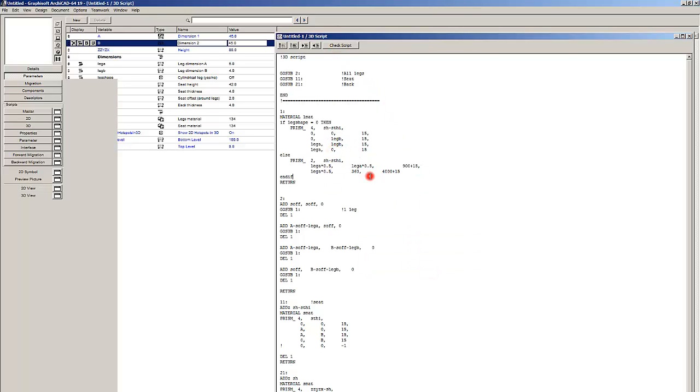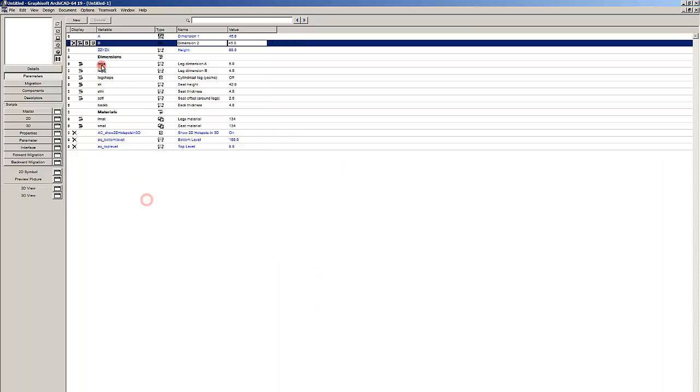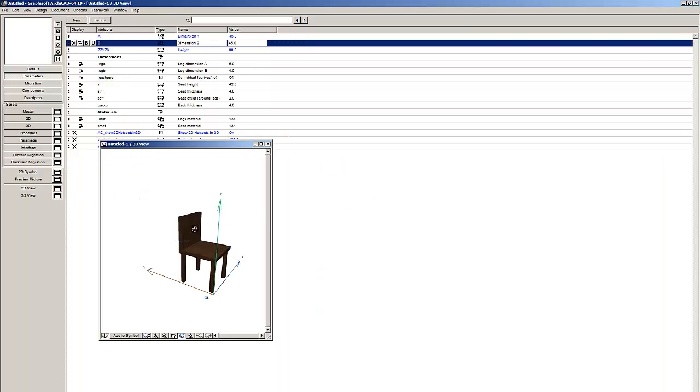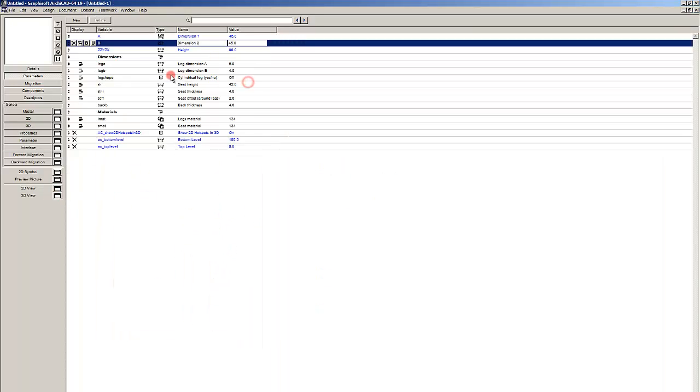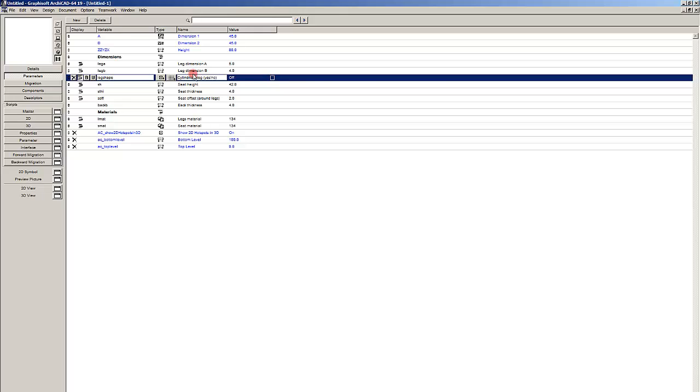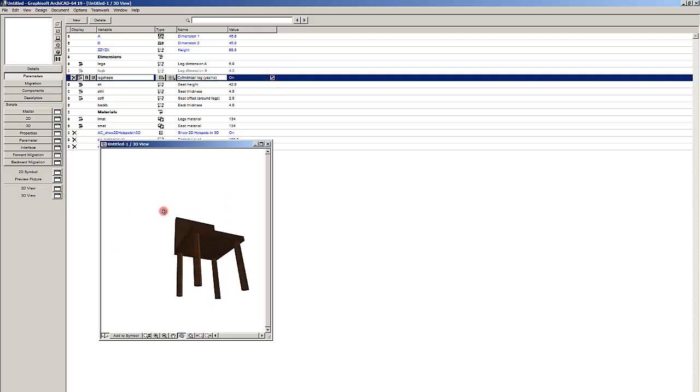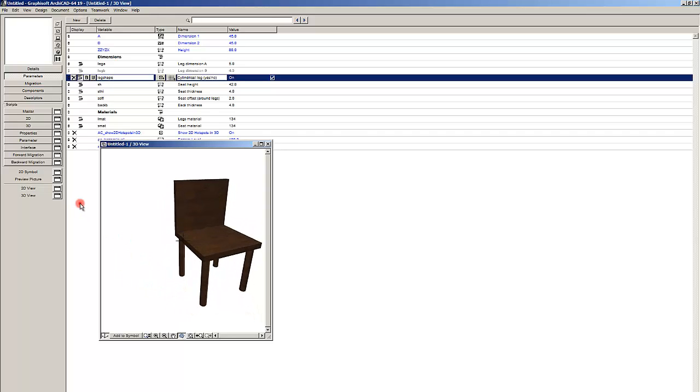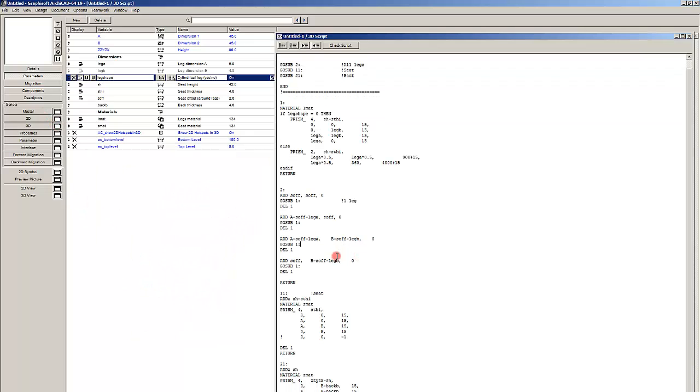And be careful with the commas when you insert them. And let's see the result. Here, since leg shape is cylindrical, we will have to switch it to leg shape is rectangular. By going on, legs will obviously turn to cylinders. And it's very useful to know this way to do it.